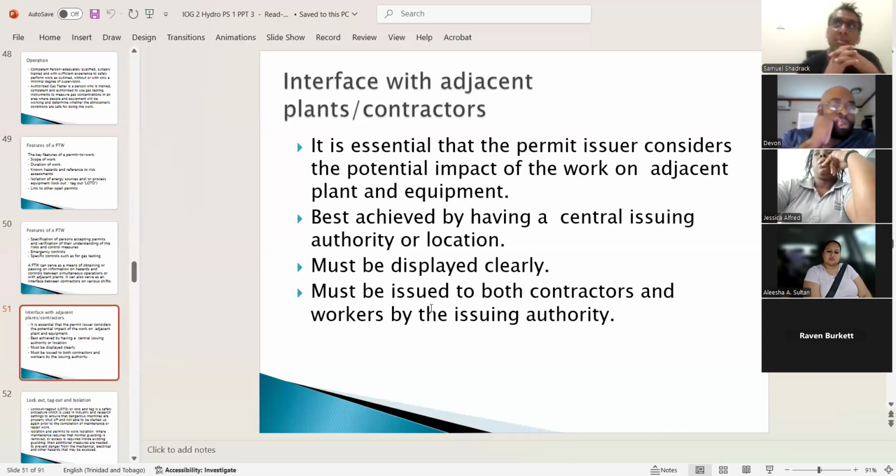So like if you were in a vessel, but then you had another contractor repairing the line, and then they're going to put back that line. Hopefully you have a lockout and tagout, but then some systems, manifold systems, have more than one line, right? So a contractor, sorry, may be away from your plant, right? They don't know that your line has been isolated. But if it's a manifold system, they may be miles away from you. They repair a line and then they're eventually going to turn that on. Now, that may feed another subline that will come into your tank with workers inside of it, right?